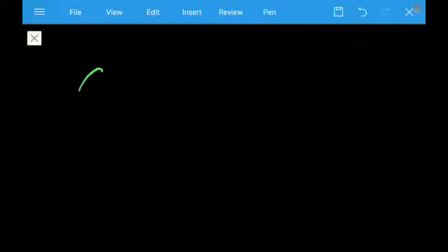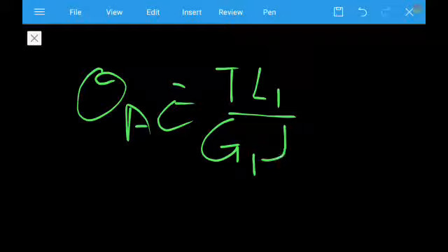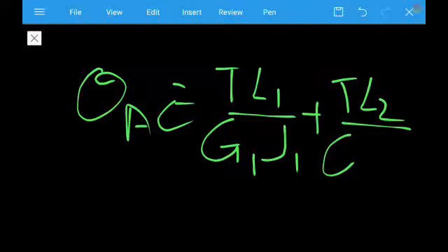Now theta AC is T L1 upon G1 J1 plus T L2 upon G2 J2.